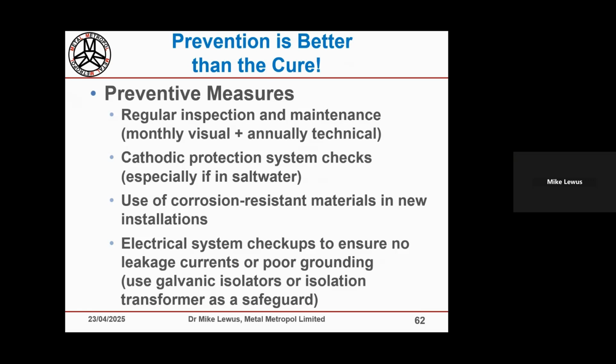Even if you remove the corrosion debris, let's say you had a stainless steel component that started off shiny and corroded, and this can easily happen with 304 or 316 in a marine environment if it's submerged, usually the corrosion debris that is produced, even if it's stuck on quite tightly, when you remove it, you'll usually find the surface is rougher. So my experience is that these things aren't usually shinier. They're usually duller because the quality of the surface has been impaired.